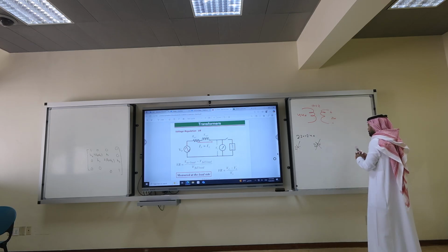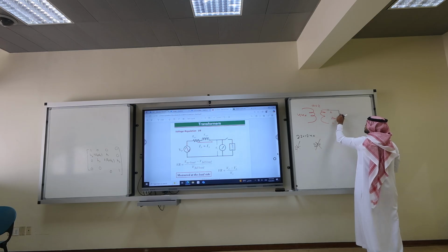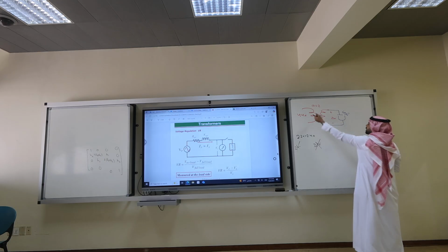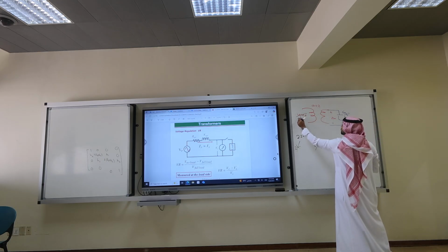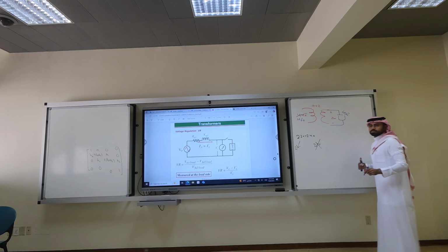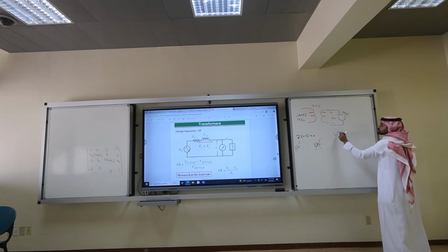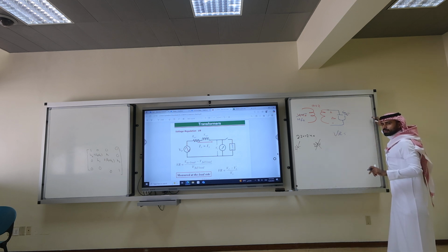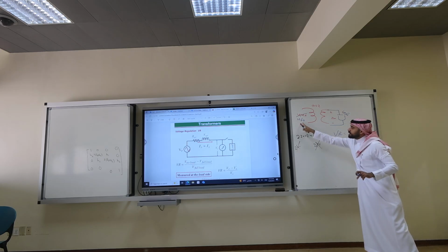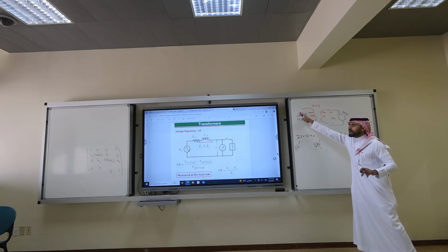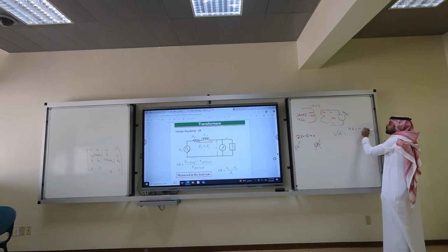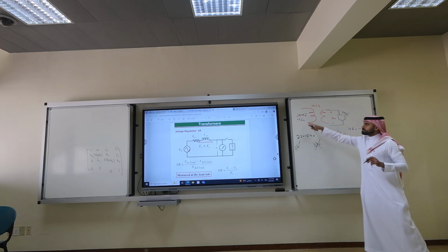Let's say I connect the load. Now the current is high, and this becomes 460. So voltage regulation is what? Voltage at no load. Remove the load. The utility has to maintain 460 no matter what. The utility cannot have 440. 460. Connect the load, 440.